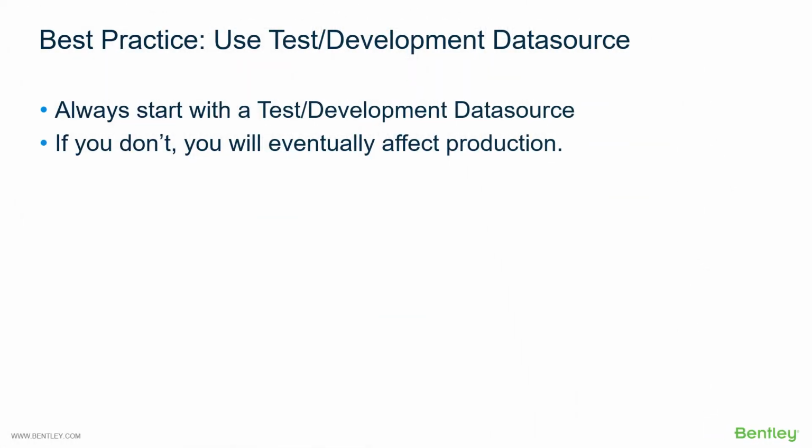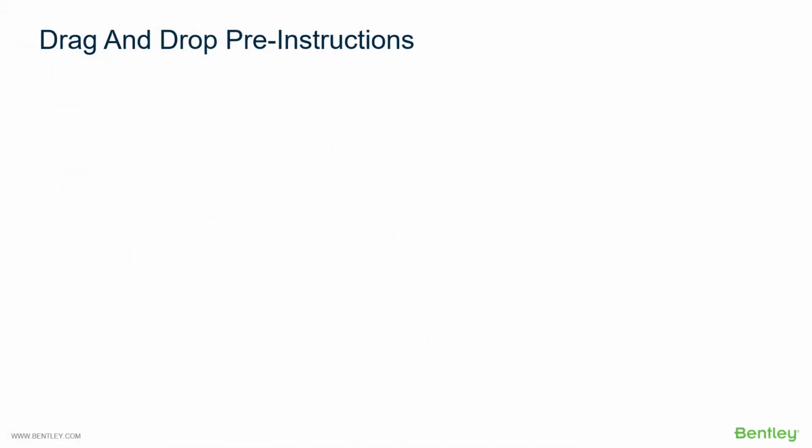As we will actually start working in a ProjectWise environment, it is recommended to always do your development in a test data source. If you don't, it's going to eventually affect your production. So, test in a separate location. The next thing we will do is import the files.